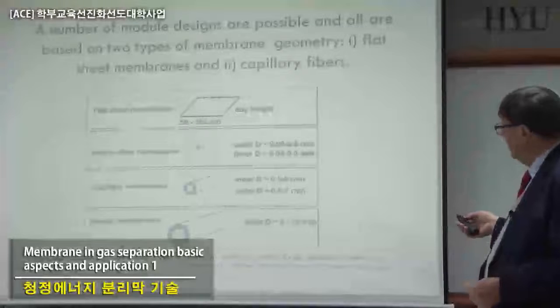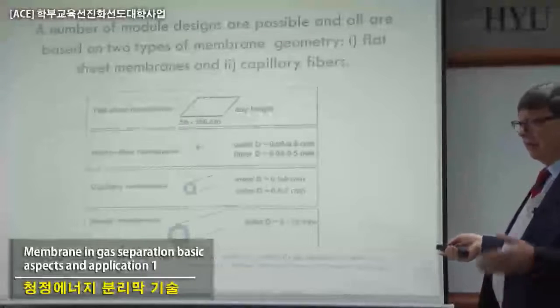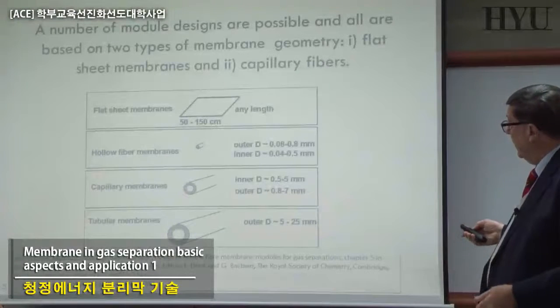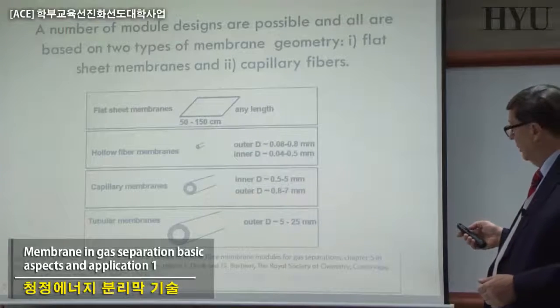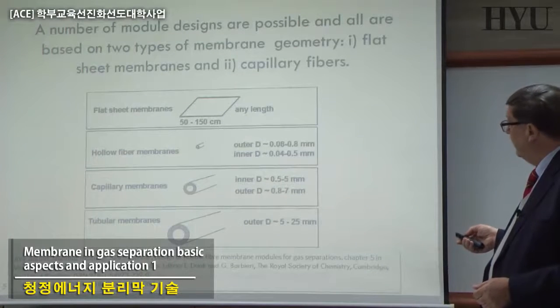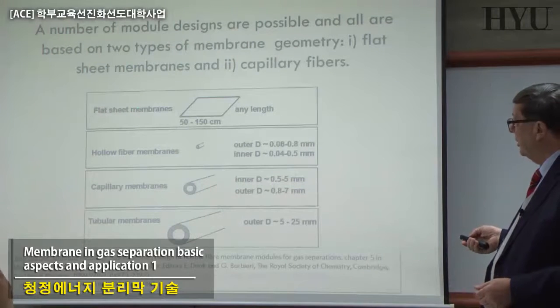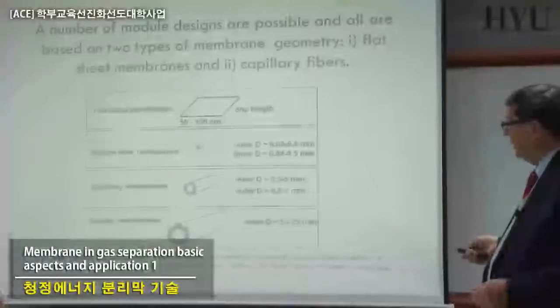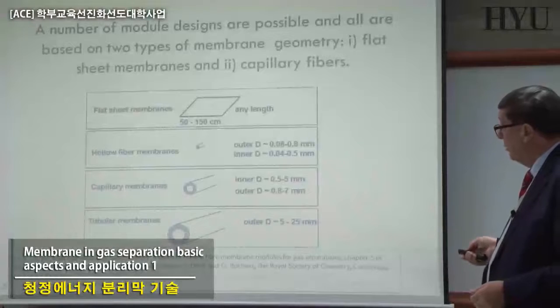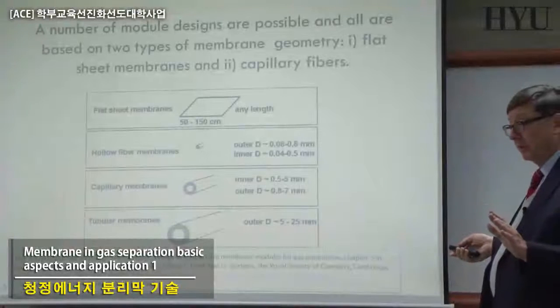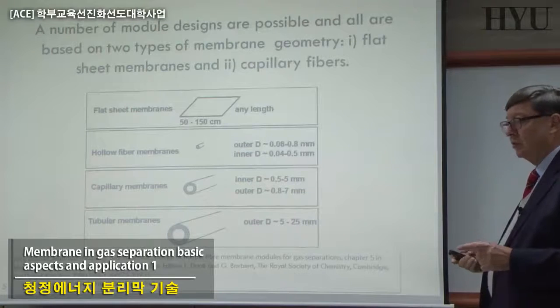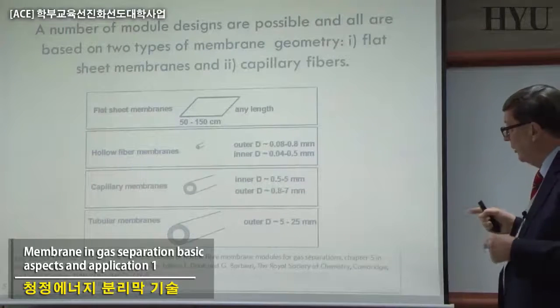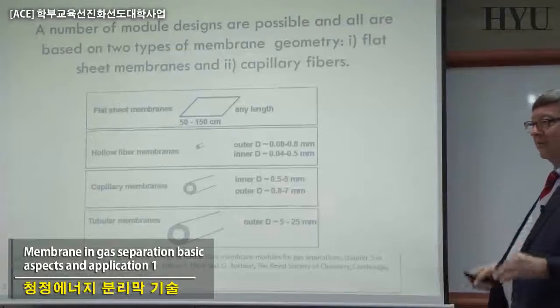First of all, the basic design of your membranes is the same as we had in the liquid phase, and you can have membranes which are flat sheet, hollow fibers, capillary, or tubular membranes. Some of them with the same material. So the motivation for having flat sheet or tubular has to be very clear in your mind. People are not doing this because they like a different design.